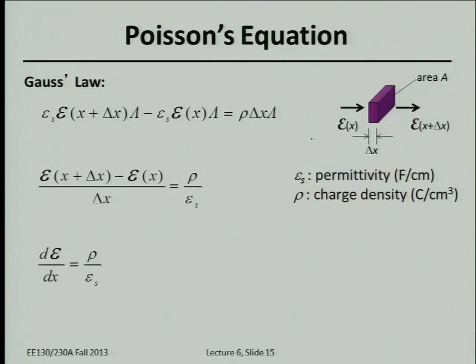Okay, so the final thing before we can start to dive into your first semiconductor device is Poisson's equation. Very simple, to keep track of electric field. Electric field affects the drift current and so on, so we have to remember that electric field can vary from one position of your semiconductor device to another if there's charge in your semiconductor device.